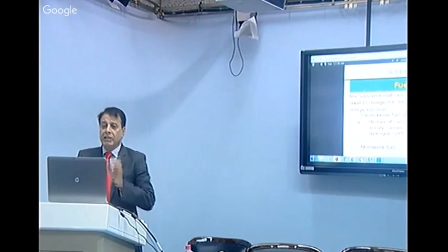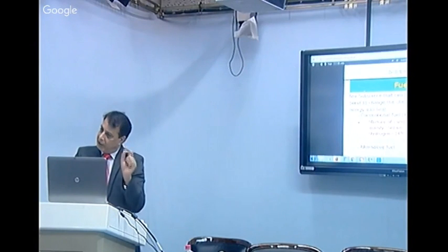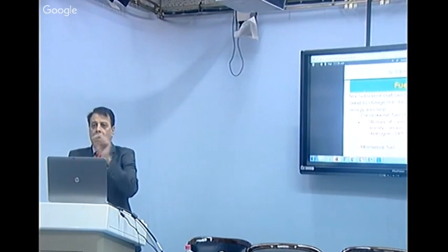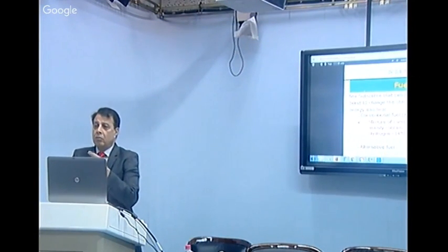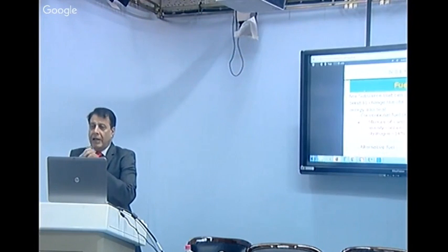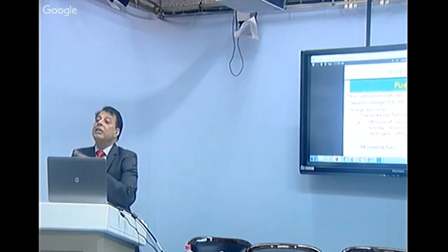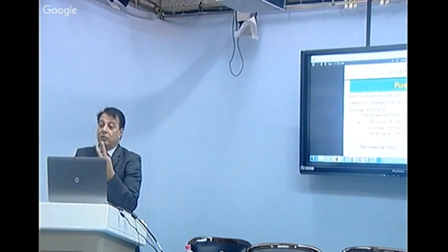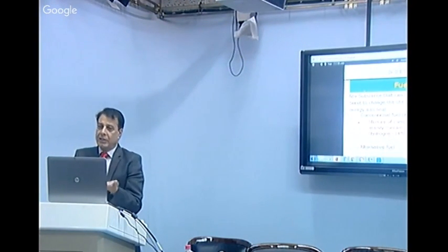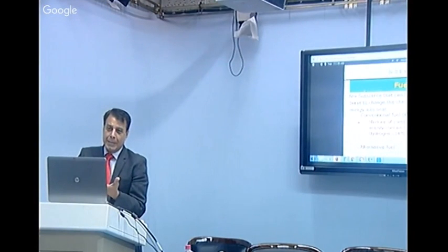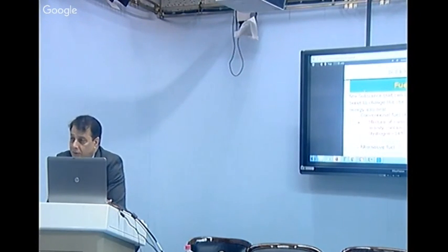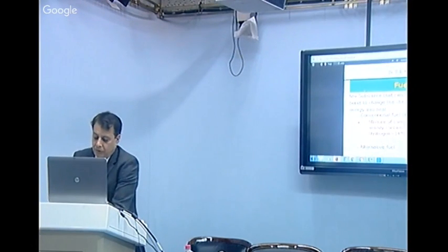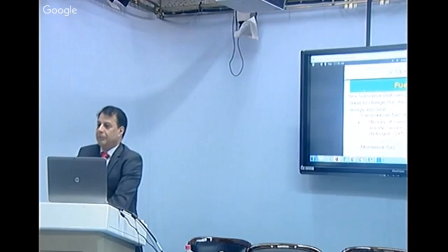Clear? So there is an abbreviation: dust holding capacity of the air cleaner, air cleaner efficiency, generally around 98-99%, and initial pressure drop and terminating pressure drop. These are the two important parameters for the air cleaner, which decide the dust holding capacity and life of the air cleaner. So what is this pressure drop exactly? Where is this pressure drop occurring? On the filter side or piston side? The filter side, across the filter.